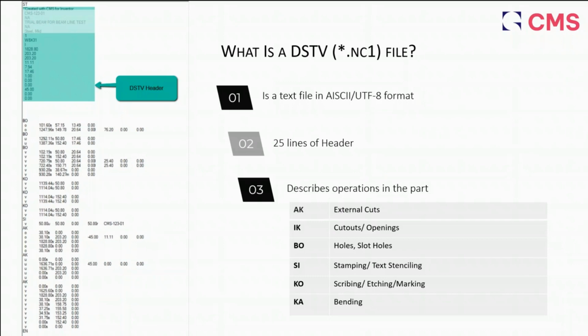So you can define where you want to place it, in which face. For example, the best practice would be top flanges, right? So if you have that part number on your iProperties, we'll grab that part number from the iProperties, read it from there, and put it on your top flange at a defined default position. You're going to give exactly where you want to see them. So if you put those values in XY coordinate values, right, then on that exact point, the software will place your text stenciling. Sometimes people call it scribing as well.